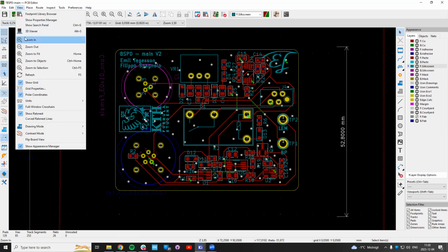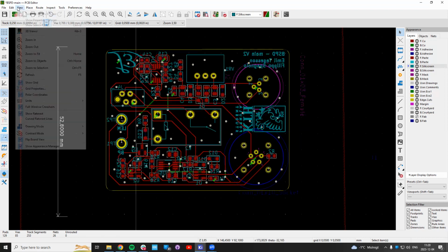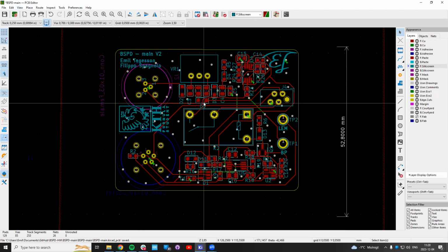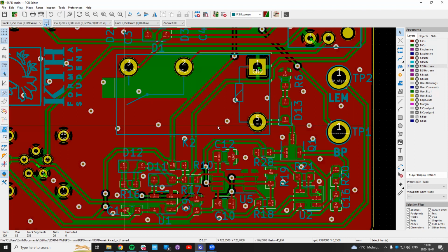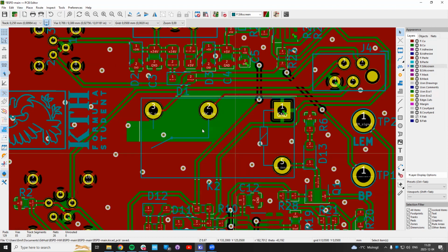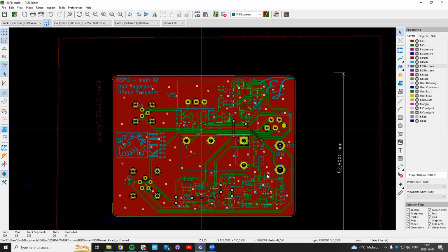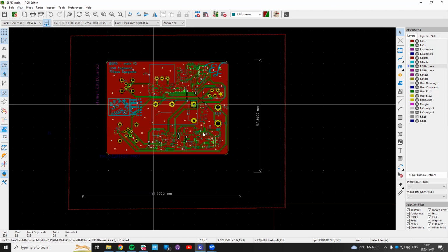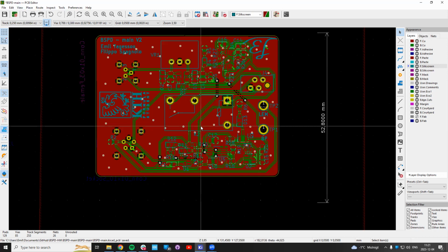Frequently use the 3D viewer. If you're working on the back side of the board, you can go to this flip board view. You change the perspective, so you're looking at the PCB from the other side. I told you already about the connectors that can intersect. Now it looks weird here because we had the text. Use this view to try and minimize these green areas, or the areas without copper, so to say. Good idea. And yeah, we'll leave it at this. We can do more advanced stuff later.